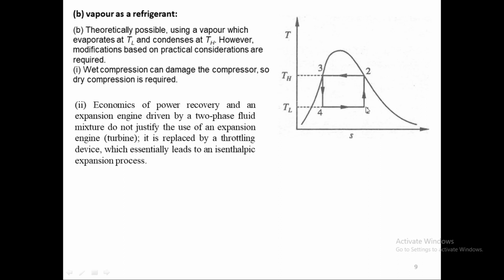If we let the liquid go into the compressor, it will make it inefficient. It will try to erode the compressor parts. It will remove the lubricant from the surfaces of the piston and it will become more rough, and more heat will be transferred, so it will be damaging your compressor. So it's not a good idea to send a mixture into the compressor. So that is one of the problems in this vapor refrigerant system.